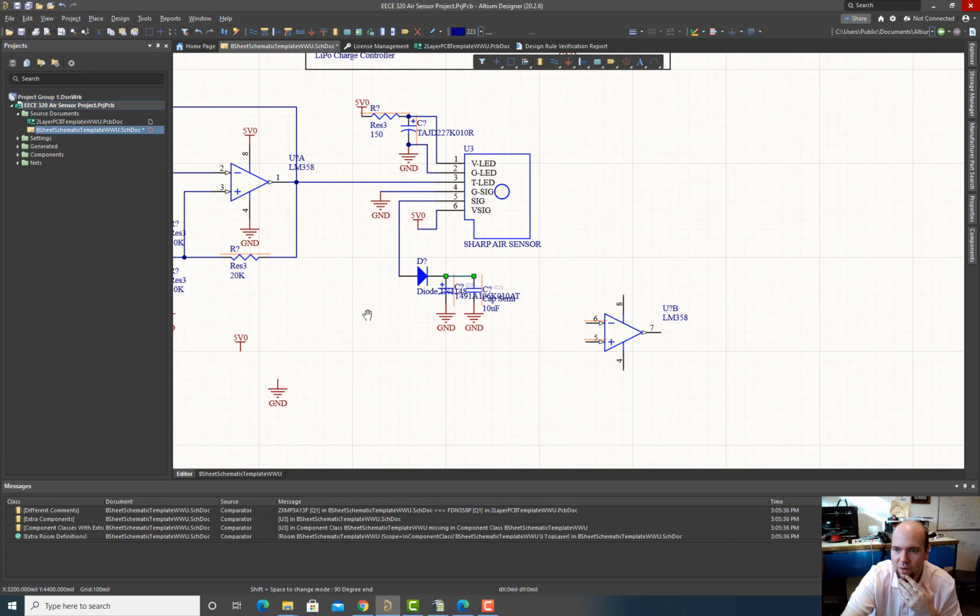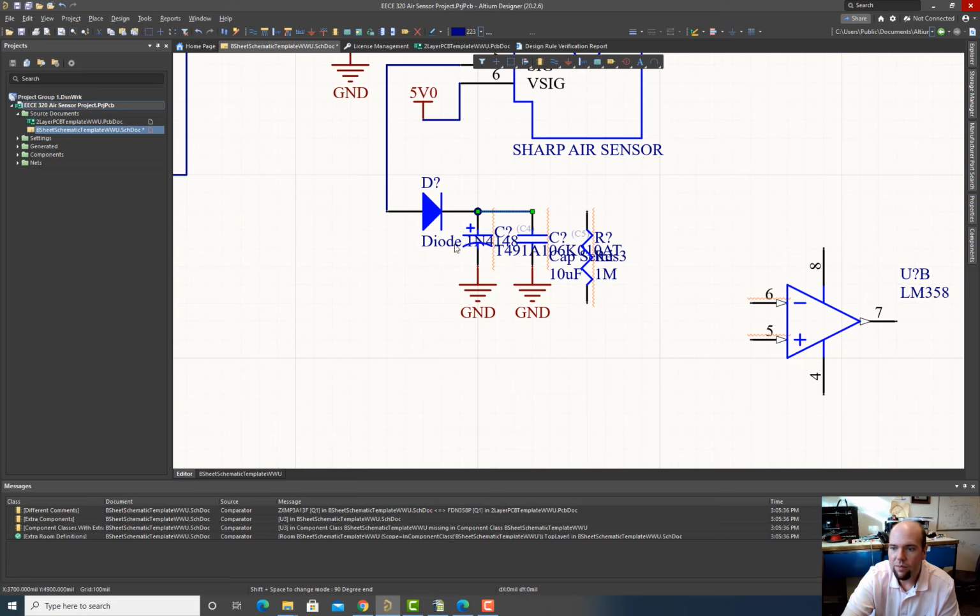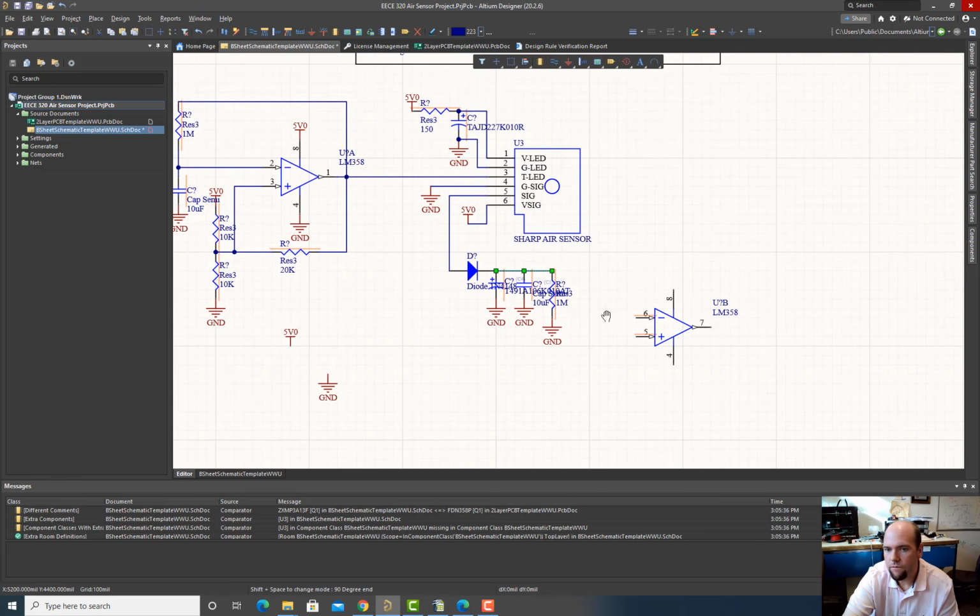So what we'll also do is put a mega ohm resistor in parallel with those. It gives us something we can control. Now this is a very weak signal. Because of that mega ohm resistor, this signal has a mega ohm supply resistance. So we definitely have to buffer this signal. To do that, we'll just do a standard buffer.